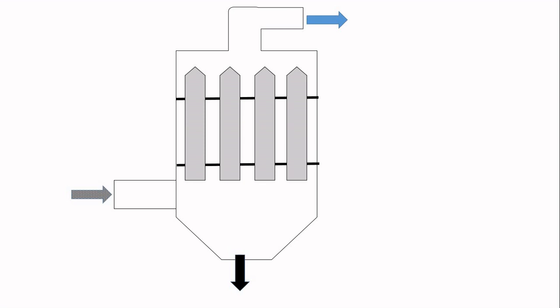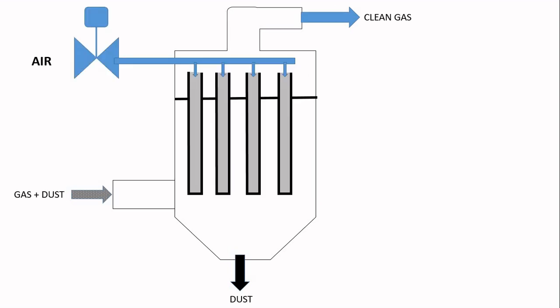So if now this is my product, you are very interested that this bag filter won't stop at all. Normally you can buy a very cheap small card which controls how the system works, and it's very important to keep it running all the time. And it's cleaned by a pulsation of air. So air pulses go into each one of those bags, or a group of the bags, to shake it and get the dust out of it.